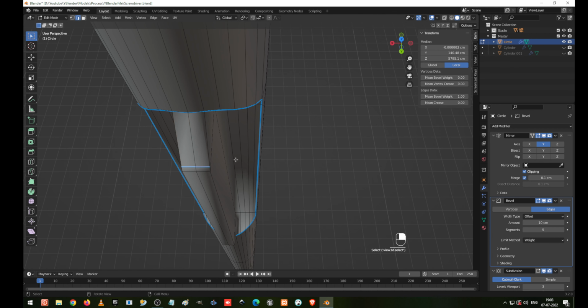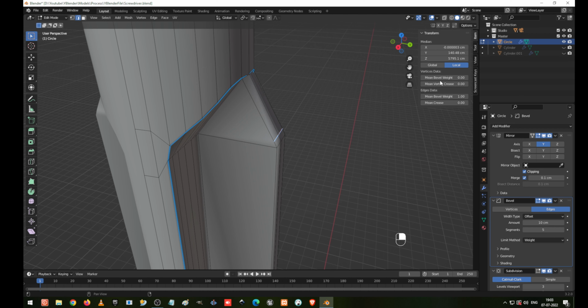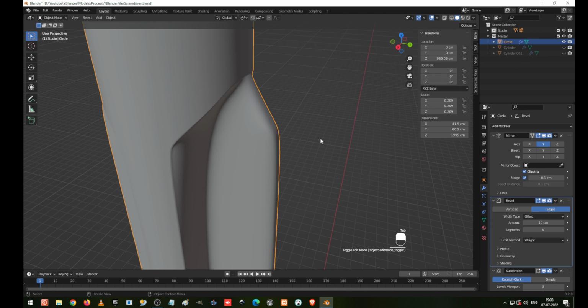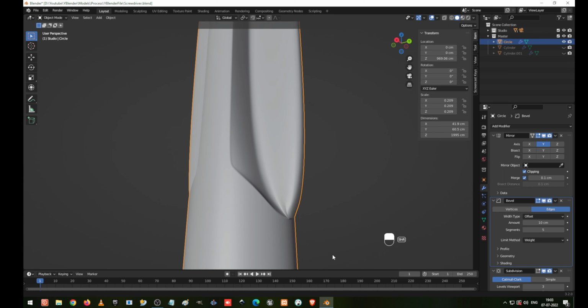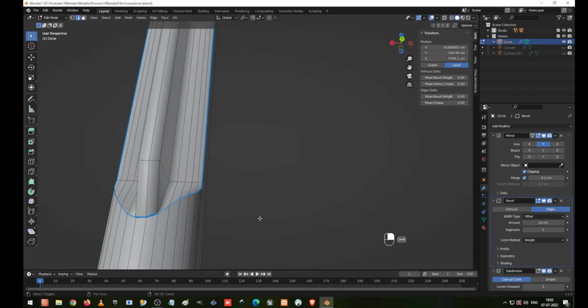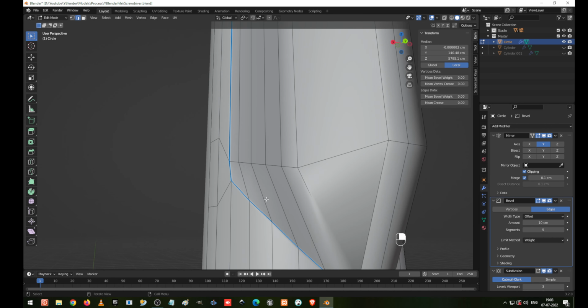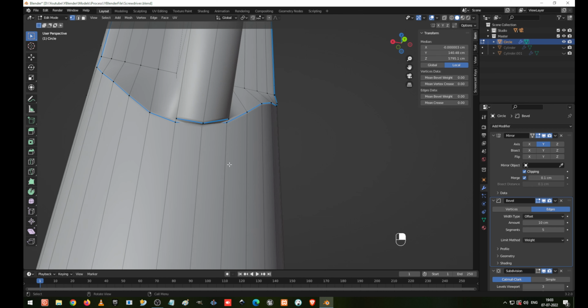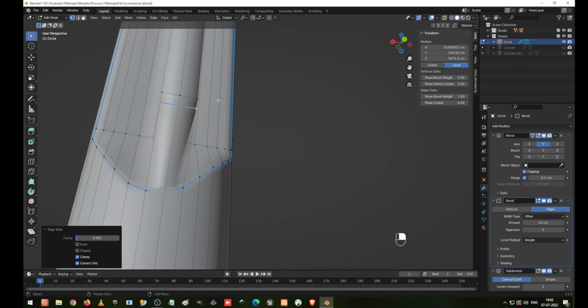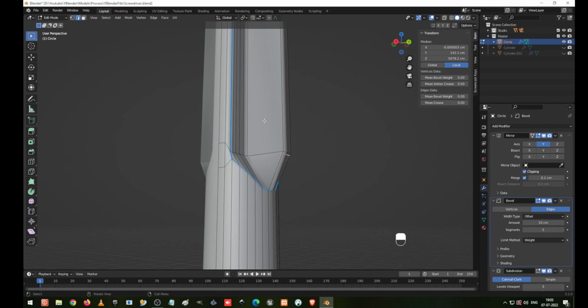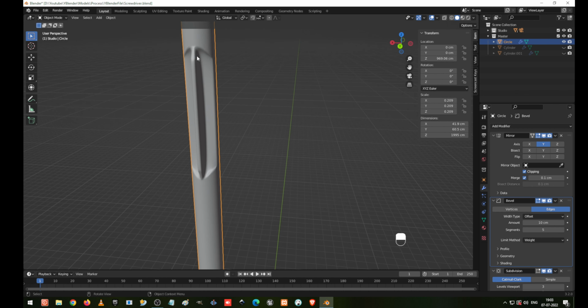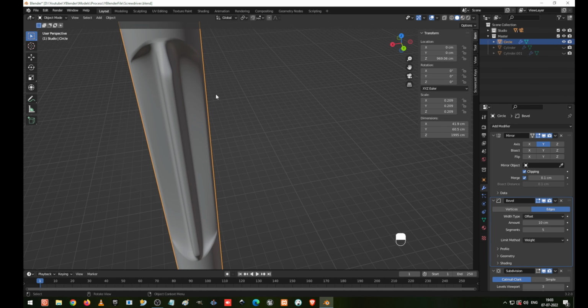and go to this beveling and turn it off to 0. Now we can see it looks better. So now I go to this, for the same I am going to do edge selection, double G to move, go to the edge selection and turn off the weight. Now it looks better, but we have to do still more.